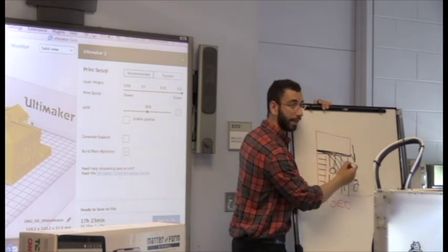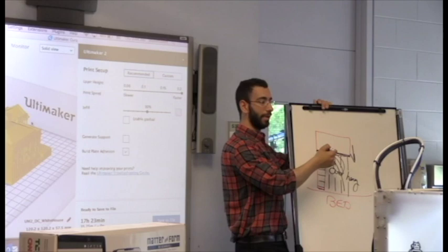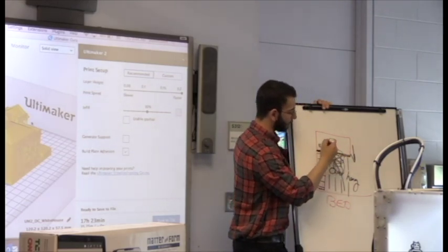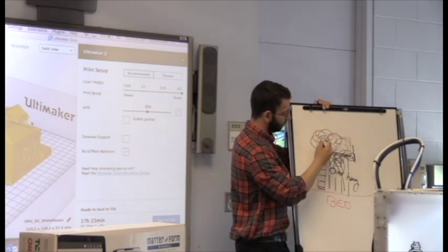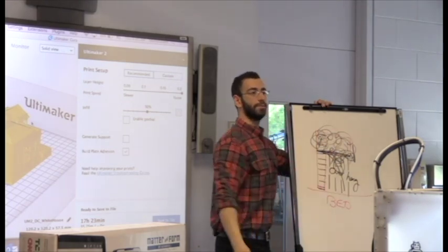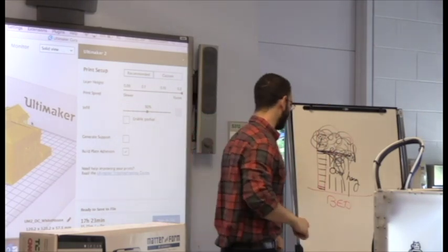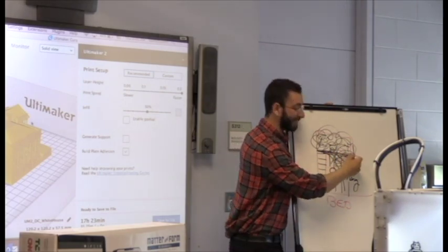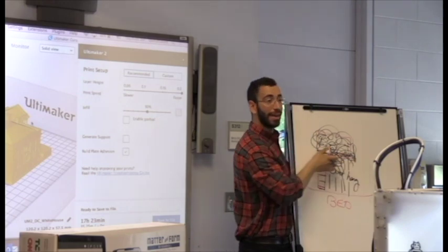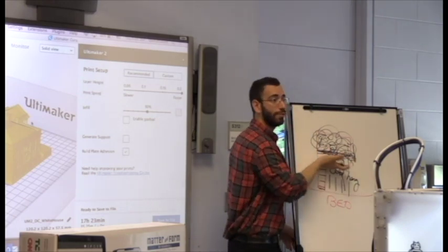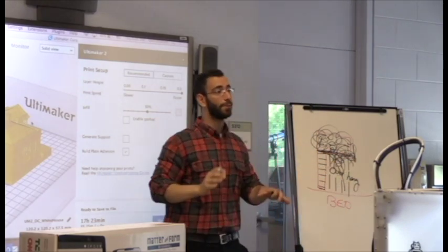It'll pull over, because once it pulls back, it's going to pull it a little bit, and it'll make something that looks like spaghetti. The top is going to look like, we literally call it spaghetti. It will look like a huge hair of filament, almost like an Afro. It'll look like that all over the place. That's called overhang. Overhang is whenever you have something where there's no structure under it, so there's something ready for that.